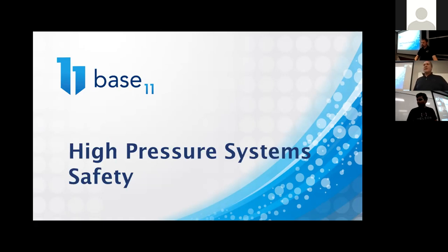Hi, I have a quick question. Yes. So, in terms of fuel systems, like let's say even alloys or propellant, what kind of fittings do you think that you can suggest? Like there are different kinds of fittings, like AN fittings, UNF fittings, and NPT fittings. Some fittings have torque values on them, but some fittings do not have torque values, like NPT fittings that I could find. So, what do you suggest in terms of fittings to make sure that the plumbing is safe?